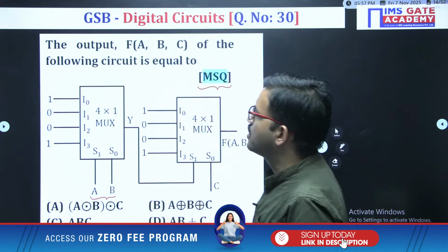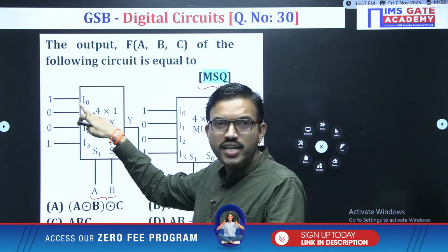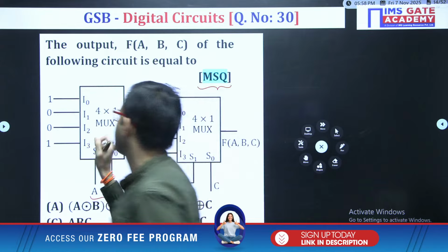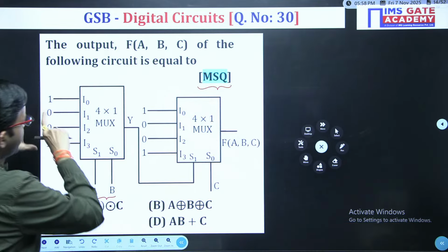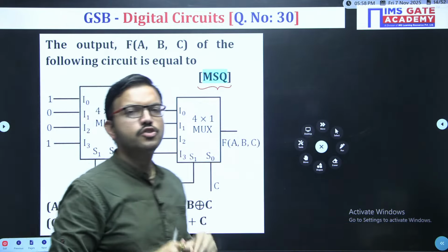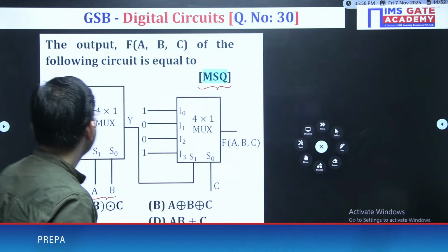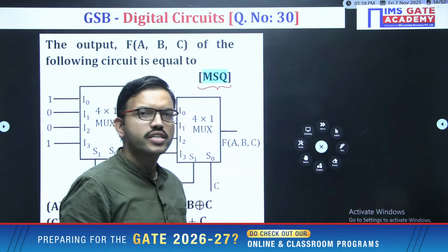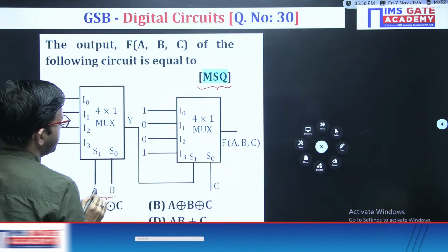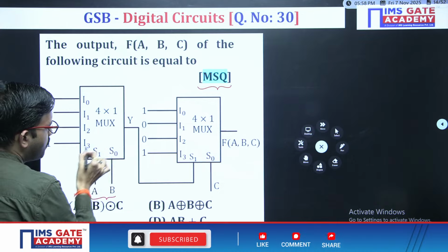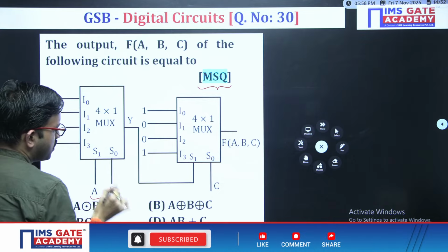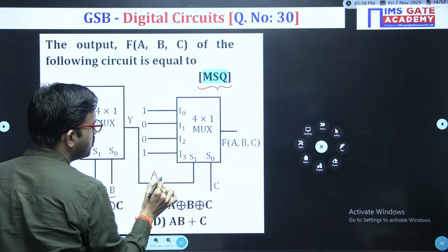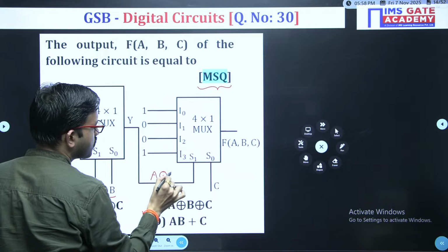Yes, the 1001 output you are getting in the two-input logic gate truth table is for the XNOR gate. So here, the XNOR operation is among the selection lines, that means among A and B, so accordingly you are getting A XNOR B.